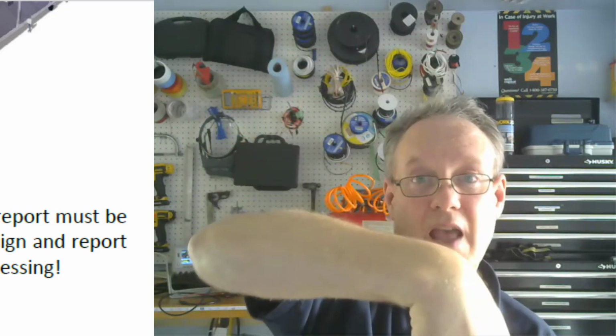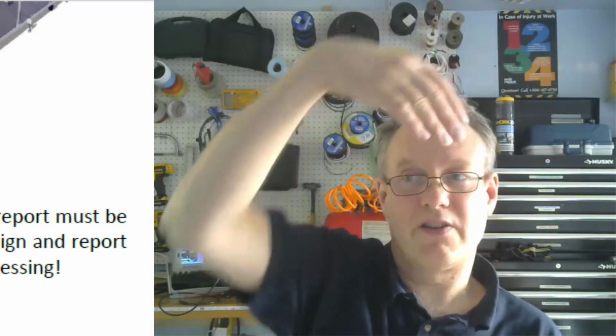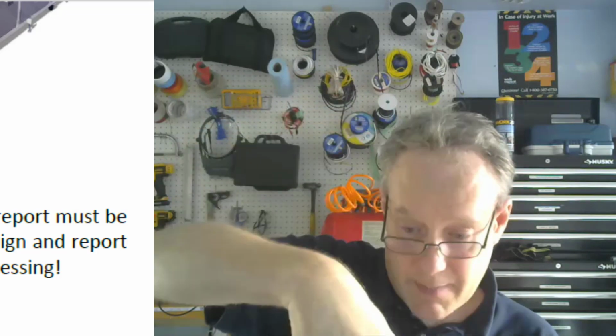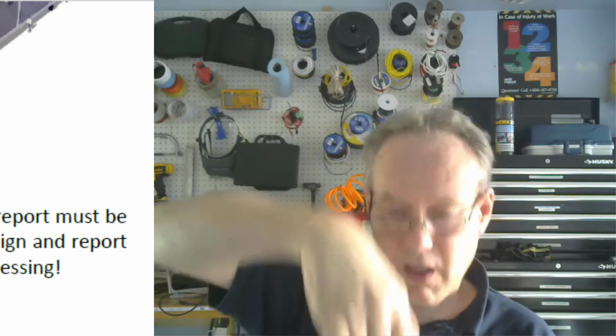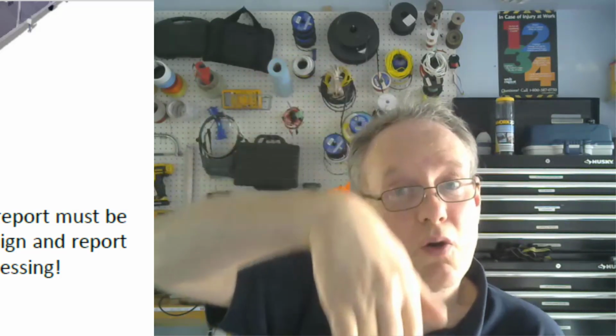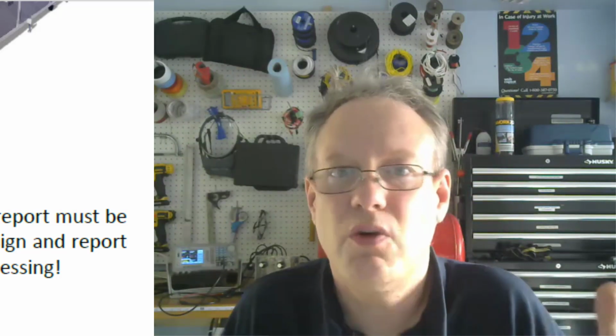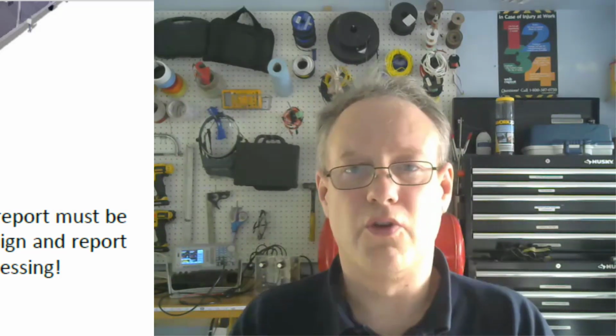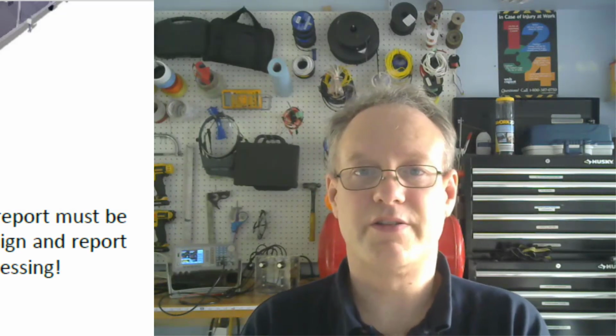Okay, good. So there's an actuator that moves the stamp down and then pulls it back up again. Now there's a timer in there that holds it, but that's the control stuff. Stamp down, hold for a little bit, come back up. That's got to move slowly on the stamp. You can't just go. Now it's a really heavy thing. It's like 200 pounds. So you don't really have to try and slow it down to pick it up, because it's so heavy, it's probably going to move up a little bit slowly anyway. So there you go. Those are the different actuators you need to put into your system.